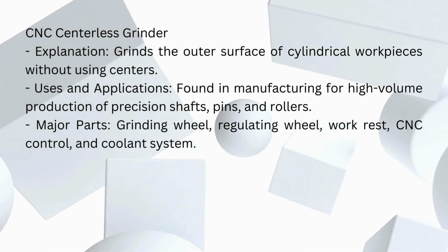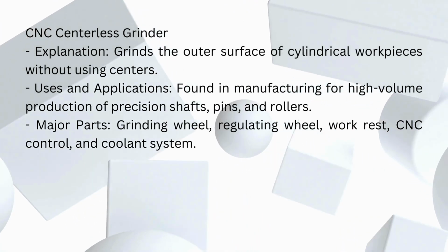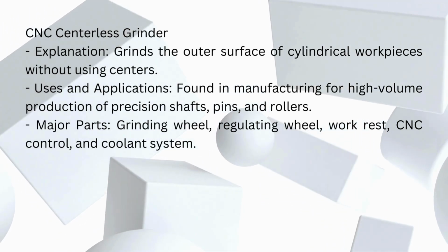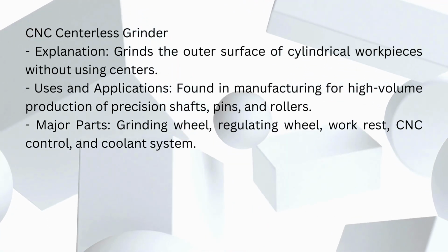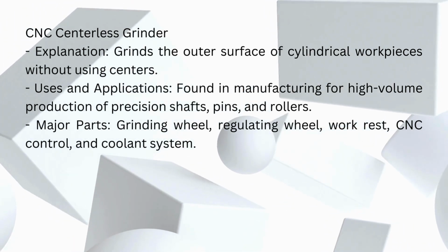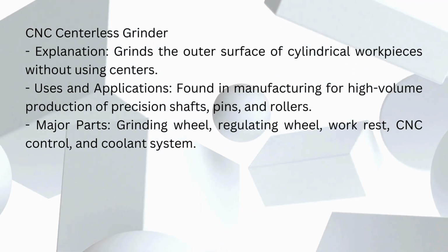CNC centerless grinder. Explanation: grinds the outer surface of cylindrical workpieces without using centers. Uses and applications: found in manufacturing for high-volume production of precision shafts, pins, and rollers. Major parts: grinding wheel, regulating wheel, work rest, CNC control, and coolant system.